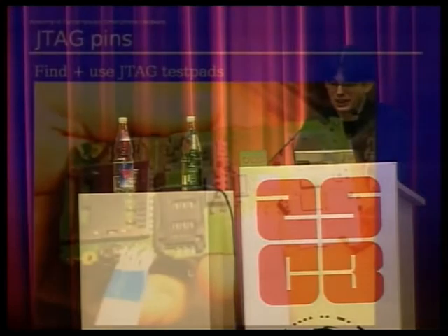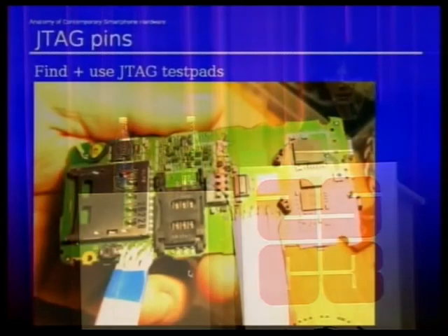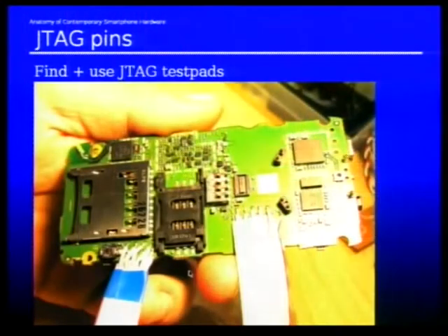Sometimes you might find schematics, which obviously then you know where they are. This is a Motorola E680 with the JTAG ports of both the application processor and, interestingly, the baseband processor connected. Just connect to the pads and try the different signals and combinations and see what happens.